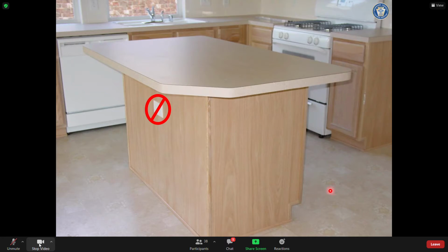Let's say that this was 5 inches. Where would you put the receptacle? I don't remember. Right here? Then it would be under this overhang of greater than 6 inches. If you tried to put it right here, it would be under an overhang of greater than 6 inches right here. So it's a determination you've got to make. If it's half and half, I guess it's the AHJ. You're making up code rules. Yeah. You would measure it from the face of that receptacle outlet to the edge of that countertop right there.